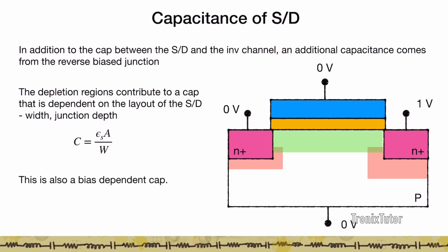So again, when you're looking at MOSFET circuits and at the various nodes, one thing to keep in mind is that almost all capacitors in MOSFET circuits tend to have bias dependence. So to do an accurate analysis for timing or speeds, you have to include those when you're doing the simulations.